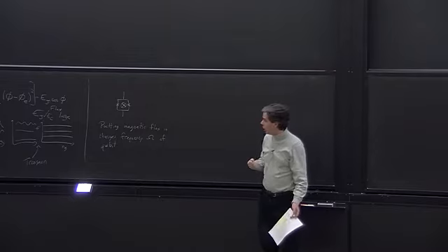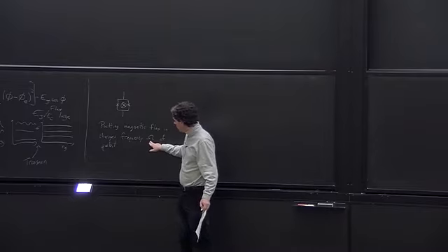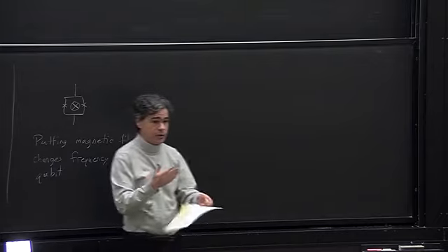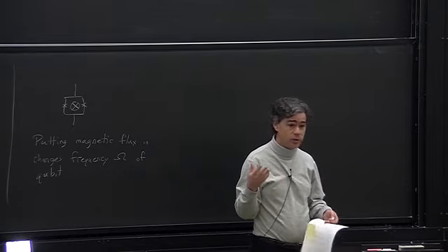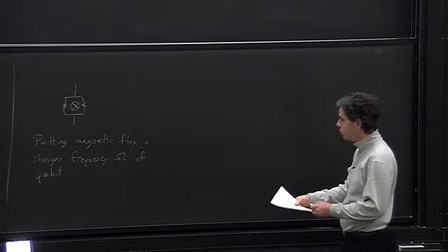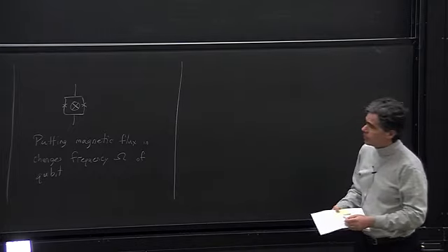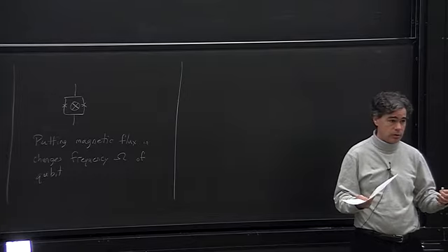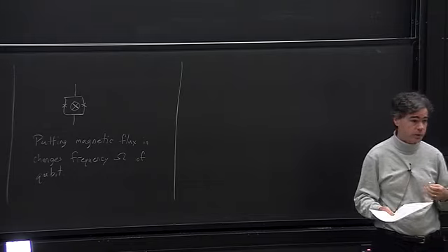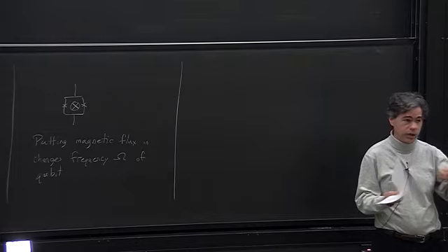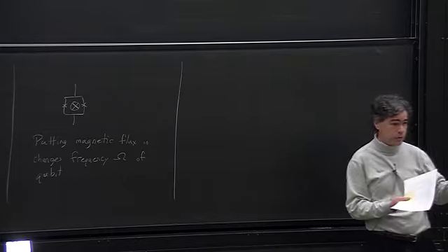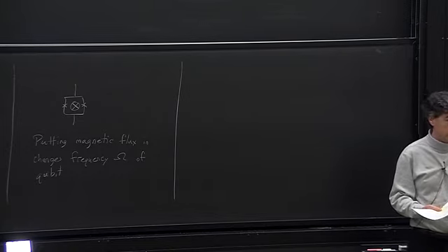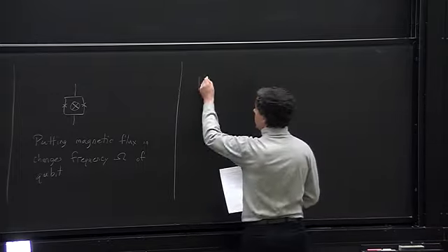OK? So the other thing that we can do with this is we can use this to put our qubit transition in and out of resonance with something else. OK? And that's another very useful trick. Another thing that happens is sometimes they'll embed these superconducting circuits in a microwave resonator, because the energy scales that we're talking about are usually microwave type frequencies. And even if you don't embed it, you might link it through a capacitor or something like that to a microwave resonator. So somehow we're going to couple this system to a microwave cavity that has a photon mode in the microwave.